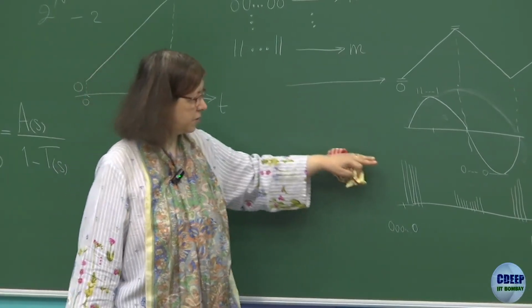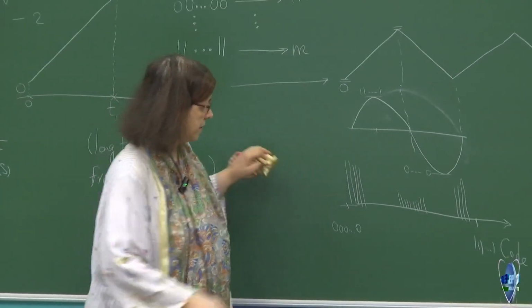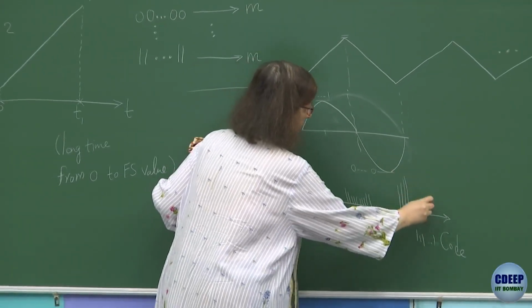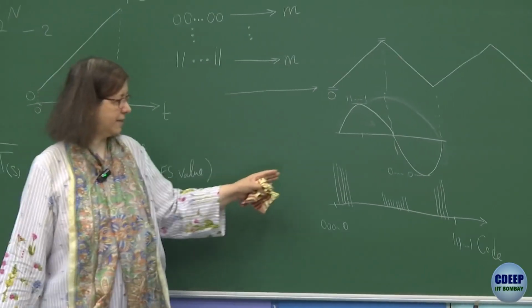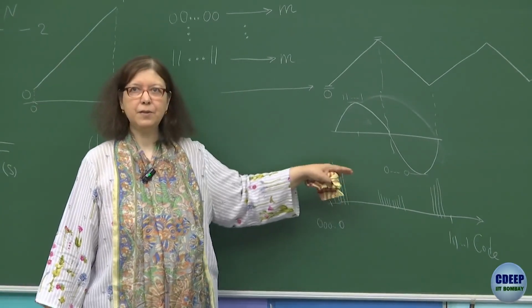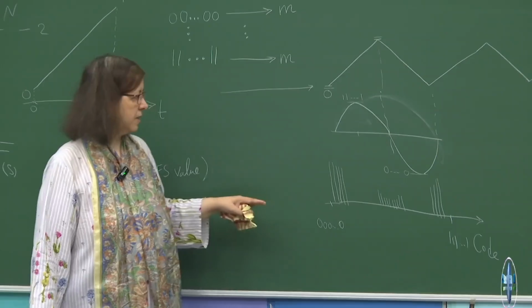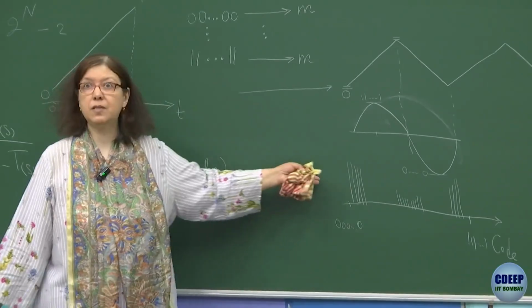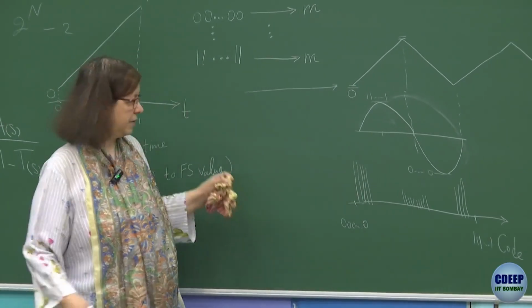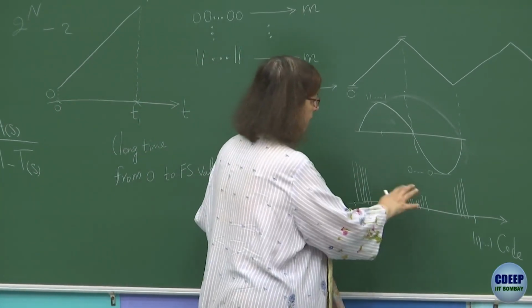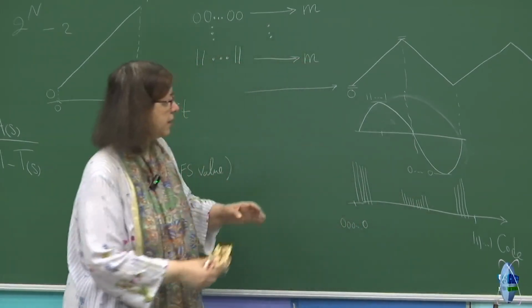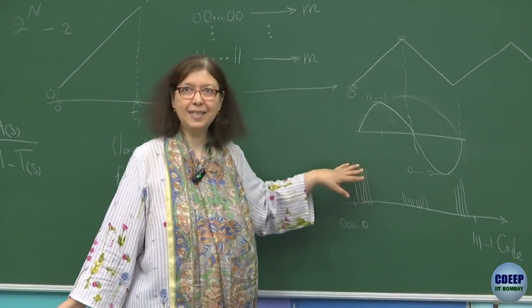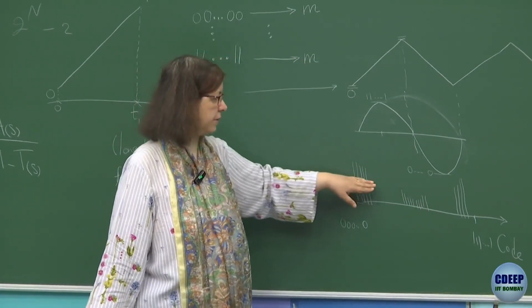So codes will have very high occurrences, then it starts reducing here, then again it starts increasing, and then again reducing. It is following a kind of shifted sine wave. So we already know what waveform we have, and now we have a new distribution. Therefore, to get the INL and DNL, instead of assuming it is uniform, we need to consider this one and get the distortion, or deviation, from that.